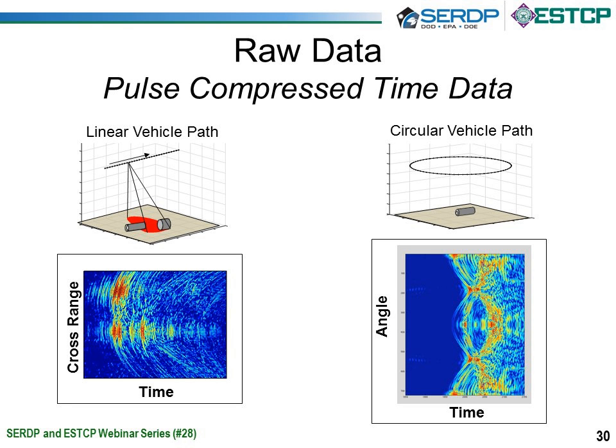So these are some examples of data products using these different scan methods. These are just the raw data before beamforming. You can see that they are very difficult to interpret. On the left-hand side, when you see unprocessed synthetic aperture sonar data, it doesn't look like an image. It typically looks like a series of arcs. And the circular scan case is even more difficult to interpret. It's what's called a sinogram. It's essentially the radon transform of the reflectivity map of the seafloor.